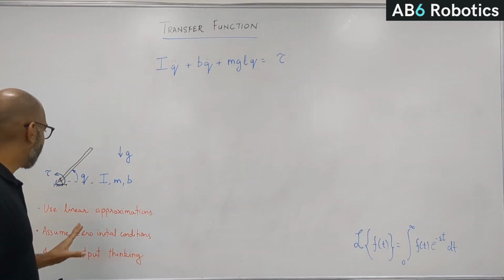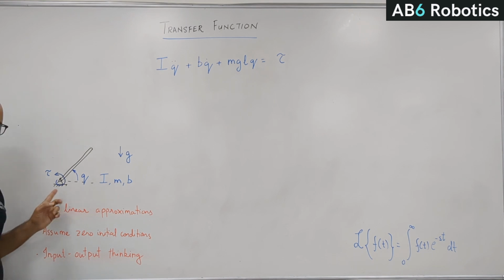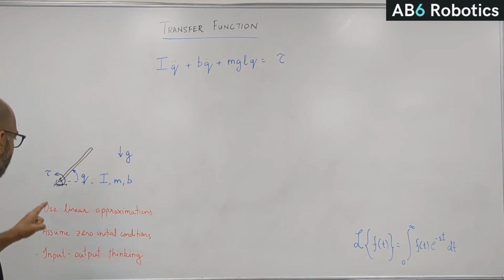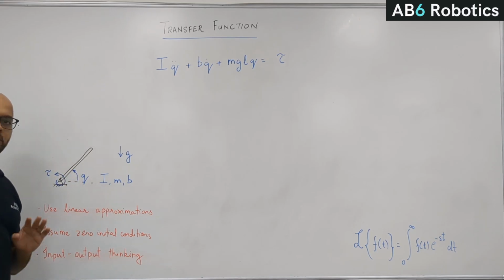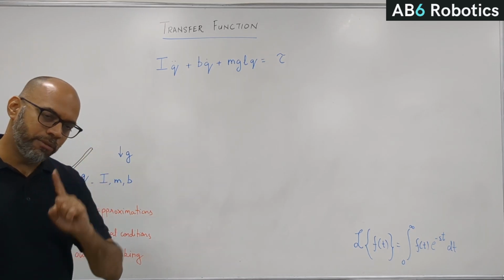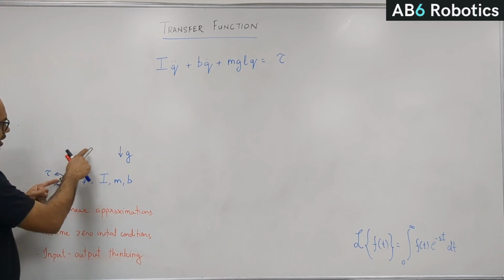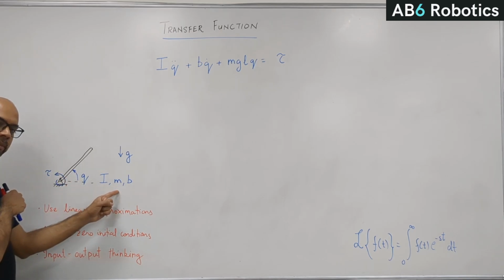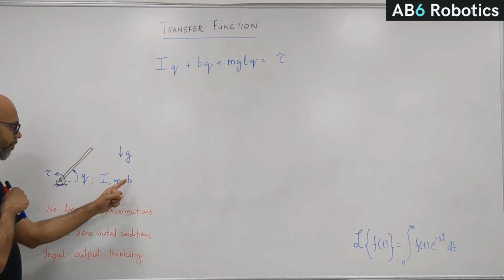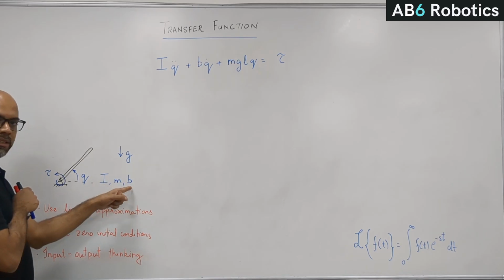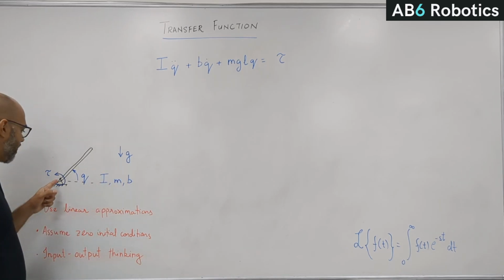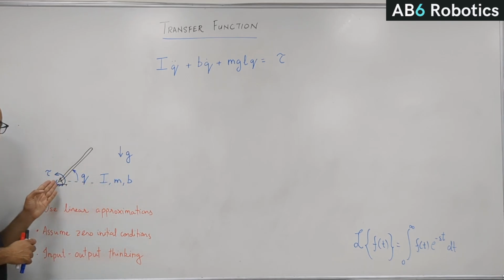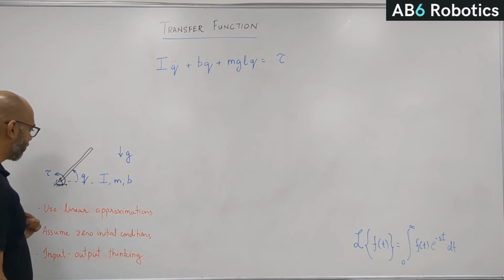First, let me start with a very simple robot. It's a single link robot, 1 degree of freedom. Very similar to what we did with the 2R manipulator, but now with only one link. So let's say there's this black link with inertia I, mass m, and now we have a new thing, which is the friction constant B, or really the damping constant B at the joint. It's capturing how much resistance to movement there is at the joint.